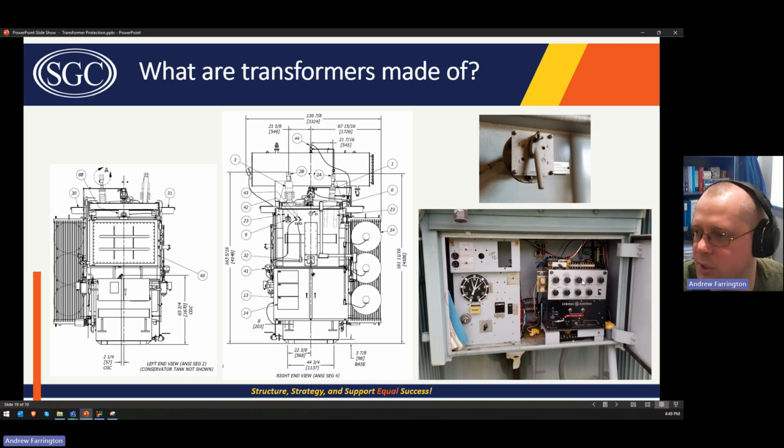And then this is a picture of a load tap changer controller. So this, like I said, is measuring the voltage somewhere on the low side of the transformer, and then these dials are setting the bandwidth. Say you want to keep the voltage at your customers at 120 volts.